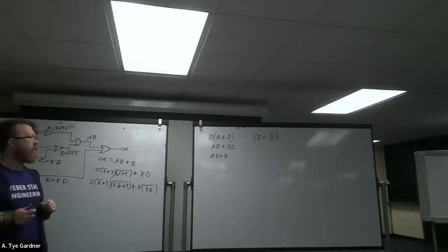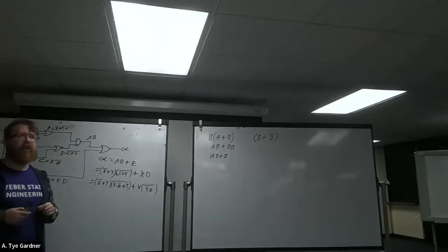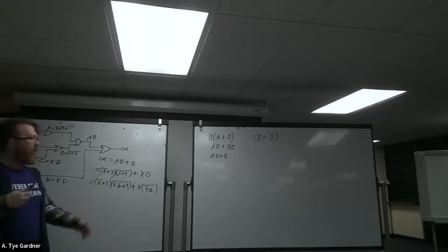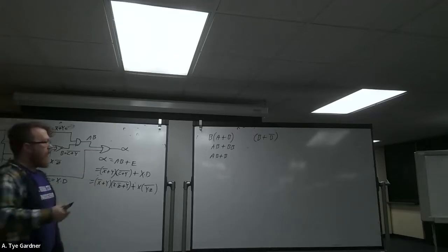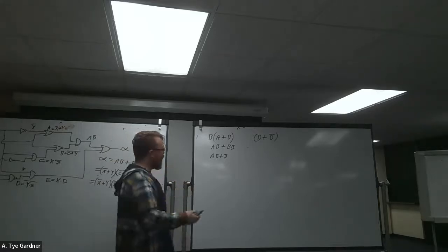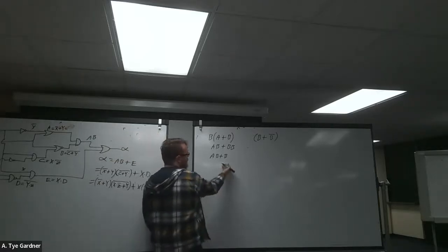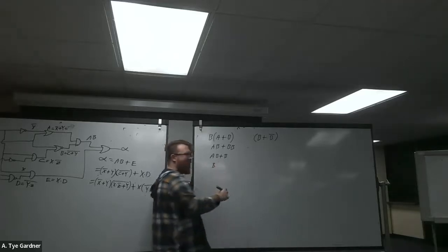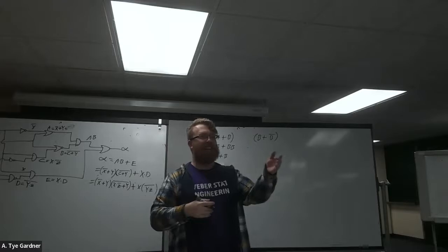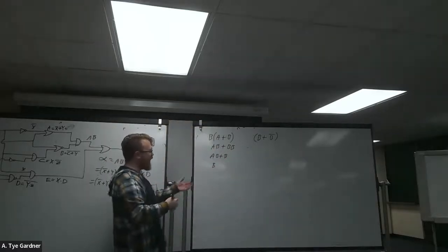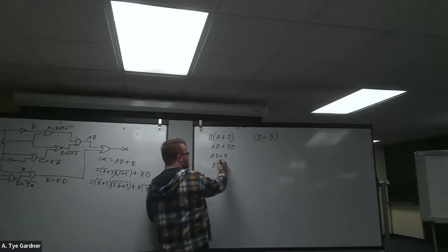Yes. So in that first one, wouldn't it flip what your final gate is to an OR gate instead of an AND? It does. Yes, it changes. And you may have to deal with the ramifications of that when you design, or it may be really simple. And you can go the reverse, actually, if you wanted to reverse this, and this is kind of fun, because you can factor things out, which becomes B, and this is actually another rule. I'm sure I heard someone say something under their breath out of confusion, and this is kind of fun. So let's factor out the B.